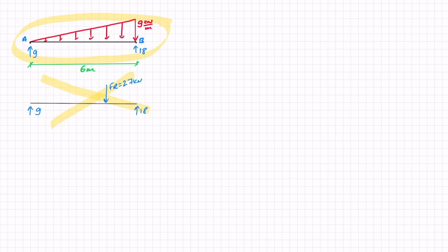First of all, this just gives me a point load, and the bending moment would look very different. It would look something like this. Whereas we can already see it would not be the same case for the distributed load. So I'd get very different bending moments.